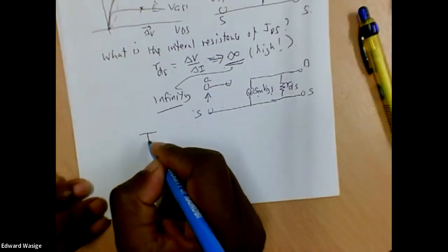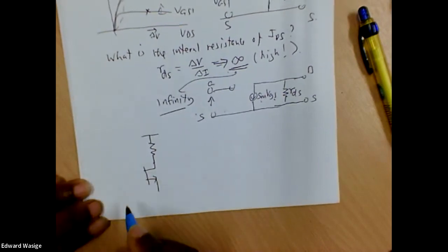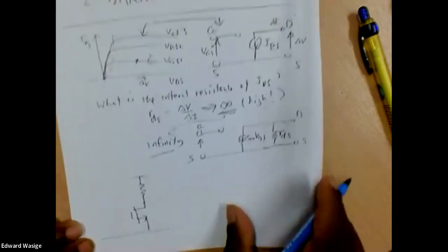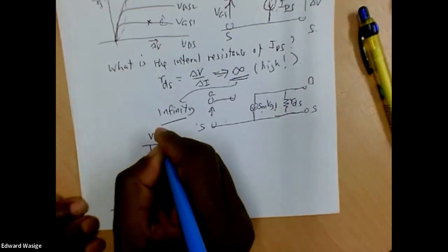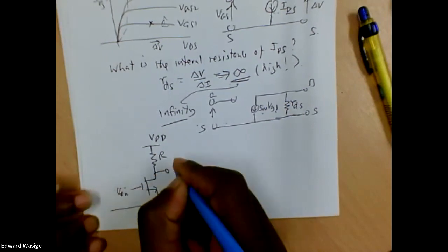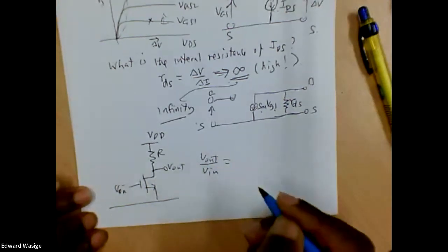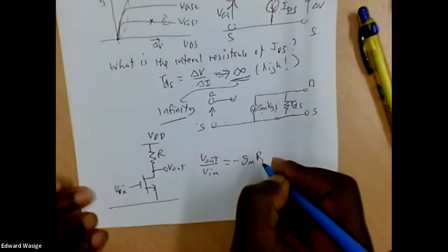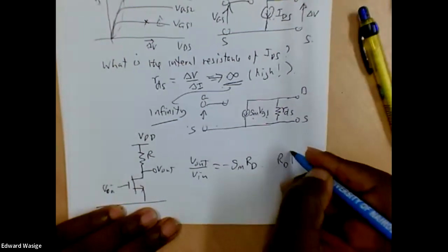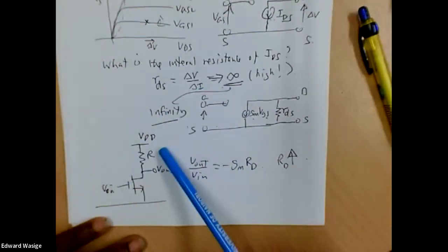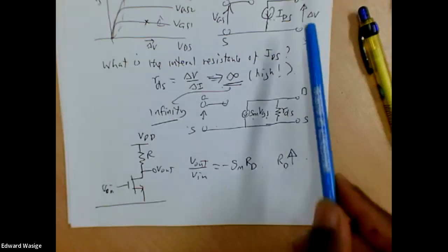And the reason I mentioned that is remember our common source amplifier. So I'll jump a little bit to point number 3 before we go back to current mirrors. We saw on Wednesday that Vout over Vin, or the gain of this amplifier, is given by minus gm times RD. Therefore, if we want the gain to be very high, we make RD as high as possible. What we do is replace this resistance with a current source.